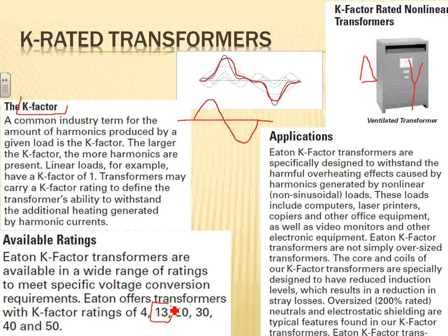Any comments, guys, about the K-rated transformers? We hear them all the time. It's an indication of the ability of the transformer to withstand, handle and absorb the heat generated by the circulated current as a result of the harmonics in the system. That's coming from, of course, nonlinear loads, which is anything that has electronics in it. Show me anything around us that does not have electronics, from an electronic ballast here to my laptop, the phone, everything else, the screens.